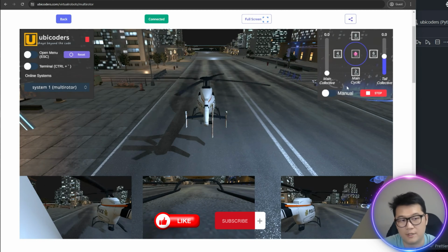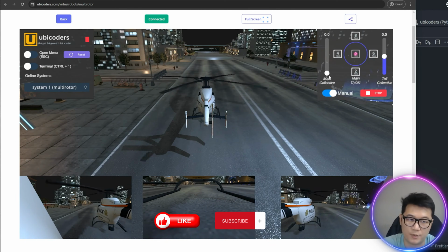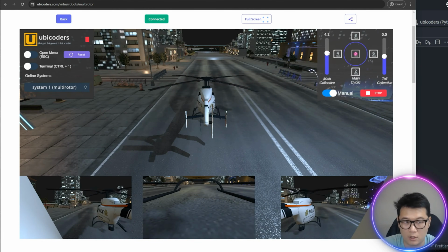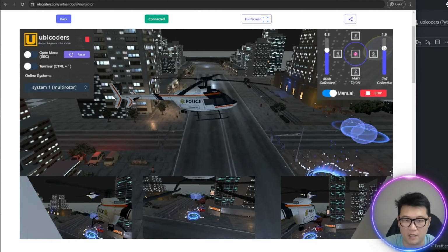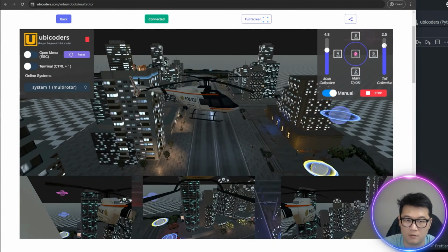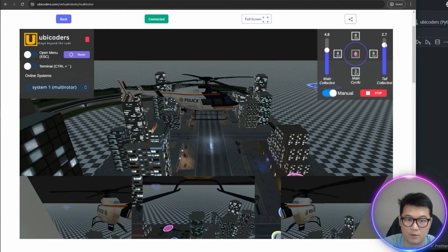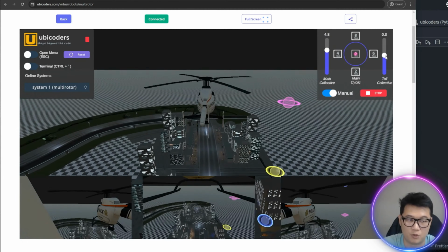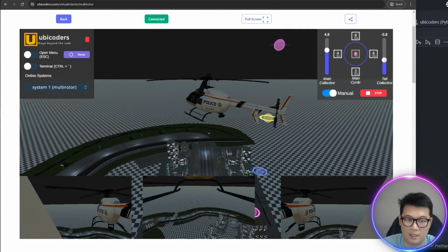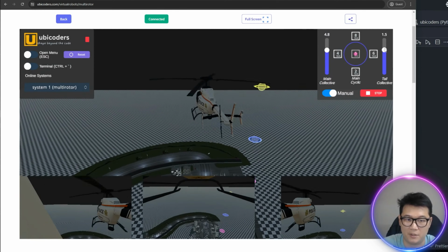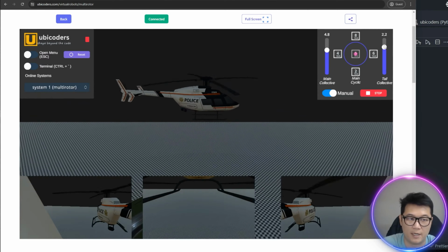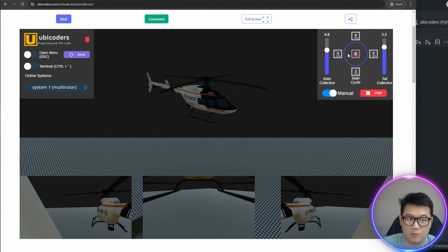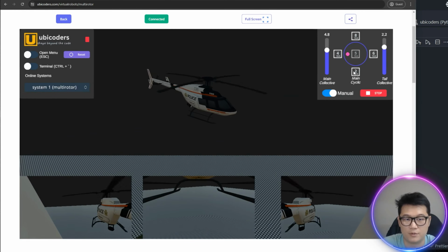So that's my helicopter, and just like the multi-rotor, you can increase the collective pitch angle of this main rotor, and then it will go up. However, because of the reaction torque from the main rotor, you need to compensate this body torque using the tail rotor by increasing the collective angle of the tail propellers. But again, it's quite difficult to do this manually. And if you want to change the attitude, for example nose down attitude of the helicopter, you can change the cyclic motion like this, then it will nose down.